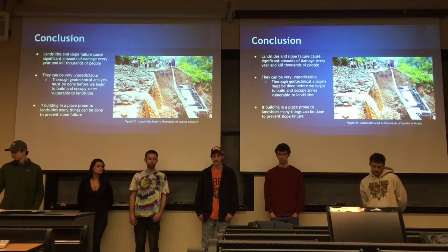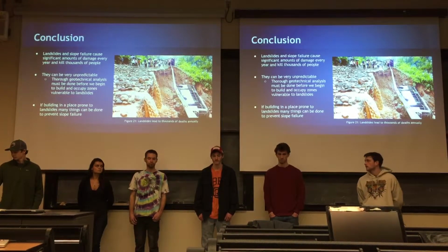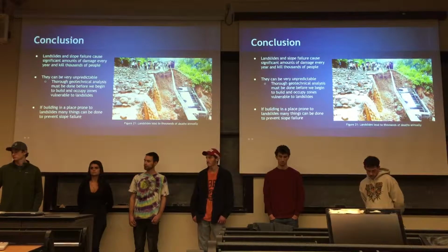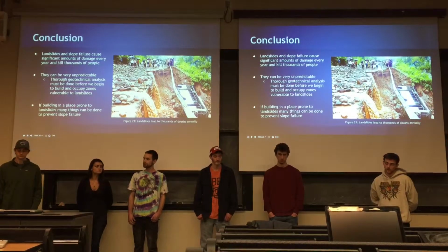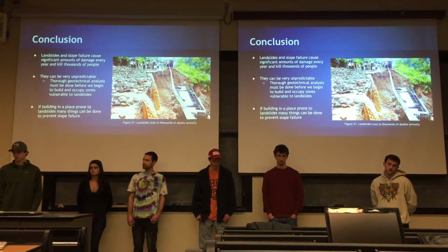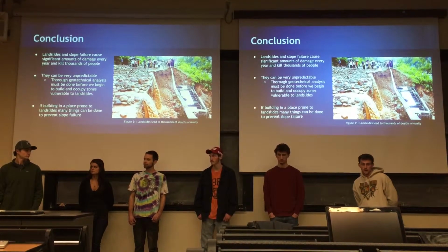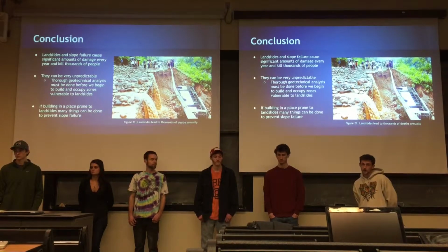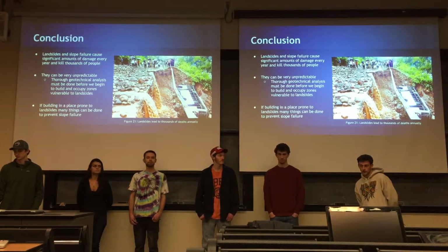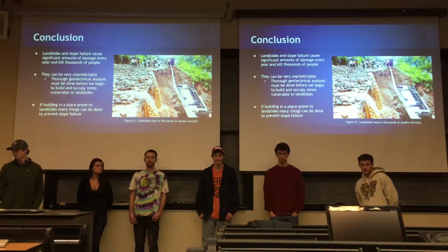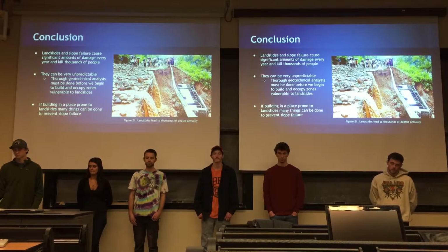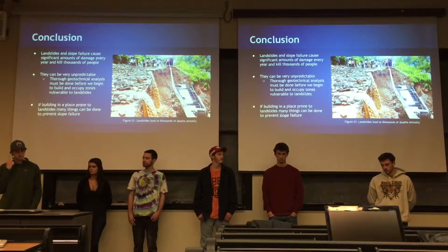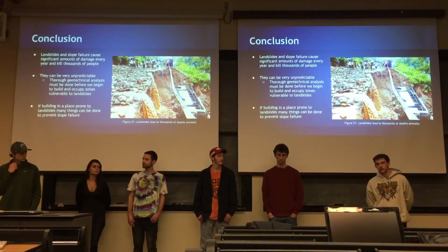But there are some ways to prevent landslides. Like I said, intense geotechnical analysis before you build on it, and then surface and subsurface drainage helps a lot. Retaining walls at the toe or at the base of a steep slope, and then piles or just support of the toe can really prevent landslides from